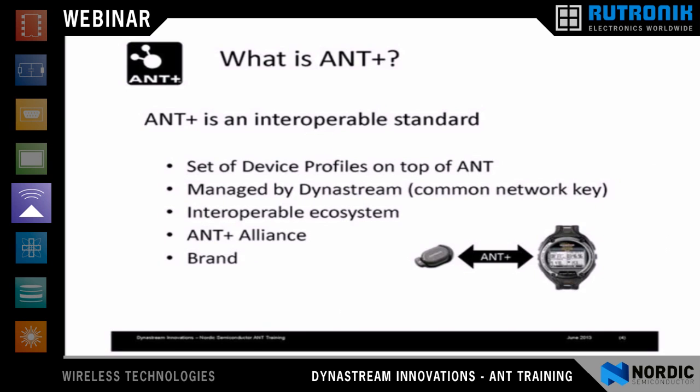So ANT+, many of you may have heard, our success has been in the sport and fitness world, and now with Samsung's S-Health and many other opportunities out there, we're becoming a strong standard within the consumer health environment. ANT+ is the definition of how the devices operate in a network and how they perform in an application. So we created a set of device profiles that operate on top of the Ant protocol, which we manage under a common network key that's shared by all of the ANT+ members.